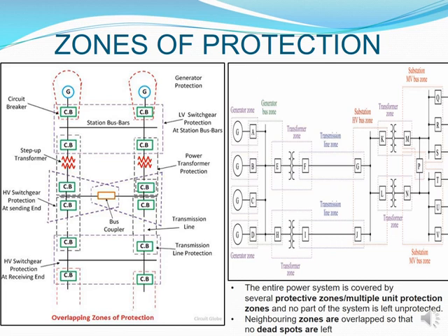Again, the nice thing about this system is if only one of the transformers was to be faulted, then the other transformers will still be able to continue with the supply so that you can still get to the substation HV bus zone. And that substation HV bus zone now is where you are going to have your G and J as well as your K and L circuit breakers looking after it.